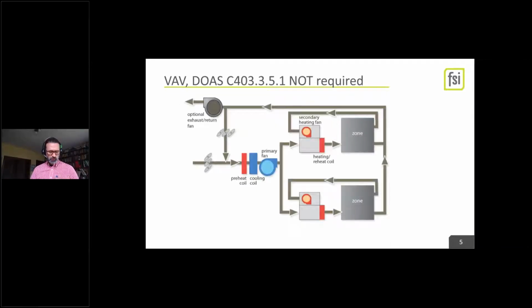All right, so I broke some of these down, starting with the most likely systems to the least likely systems. There's a tremendous number of variable air volume, VAV systems out there. Rooftop unit and some sort of VAV box with reheat coils. So this is straight off Trace for those of you who are using it. This is the rooftop unit, preheat, cooling, and then secondary with a reheat coil. It's a parallel box or series box or just a pinch box with reheat. There's a bunch of ways to get that done under the more modern code.